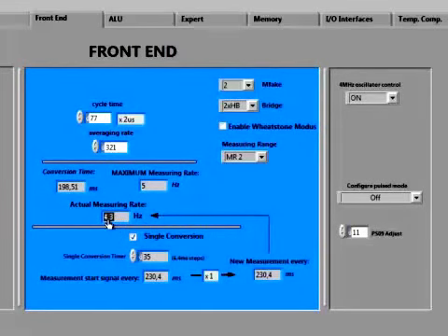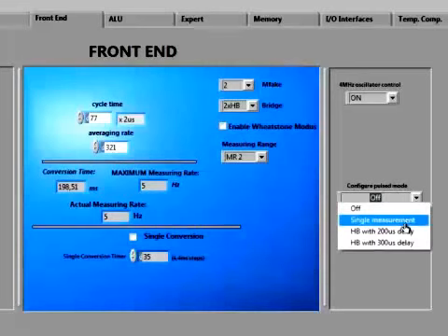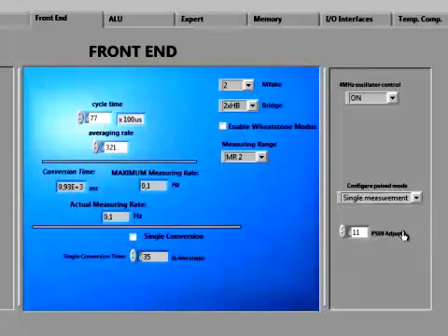The third measurement mode, described as the stretched mode in the PS09 datasheet, can be configured here. Here it is called the pulsed mode. Once the stretched mode is selected, the cycle time is automatically set in multiples of 100 microseconds.